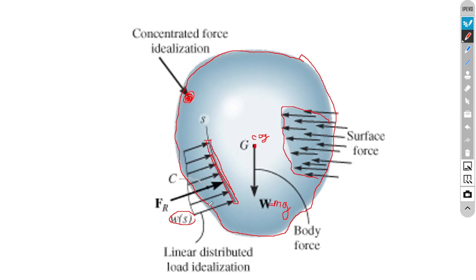Okay, if the externally applied loads are those, then for instance at this cross section, imaginarily cut the body and answer the question: at this cross section, which forces have to balance the effect of the external loads?